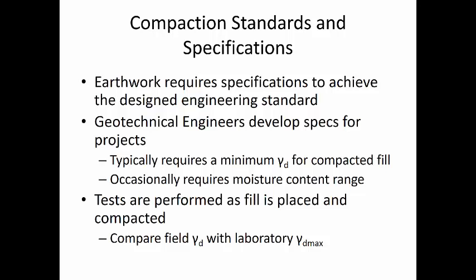Once you have those specifications in place, then tests are performed on the fill material as it's being compacted to verify that the field unit weight is comparable or within a specific range of the laboratory dry maximum unit weight that is determined through the Proctor test, which is what we're going to talk about.